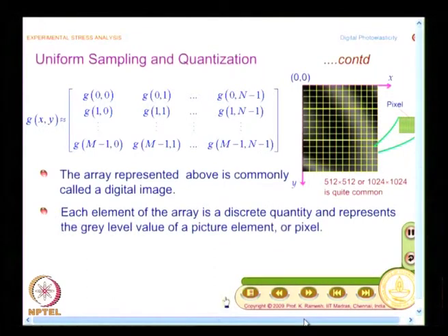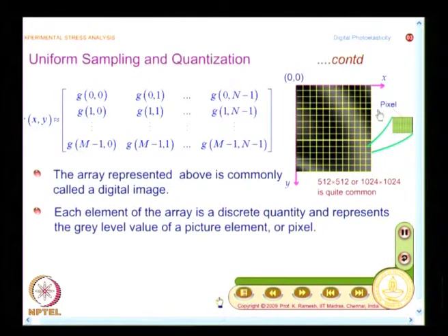and what you will have to keep in mind is, what we call a pixel is a very small area. By appropriately using a lens, you would be in a position to even go to the stress concentration zone and, when you have very high fringe density, get a decent resolution at the camera plane. So, I can have an optical magnification and then enhance the features in the stress concentration zone. That is how people solve it when you have a very high fringe density: they optically magnify that zone, then take it up in your digital image and appropriately process it.